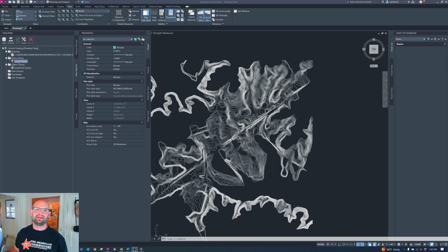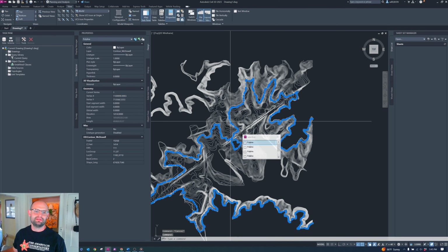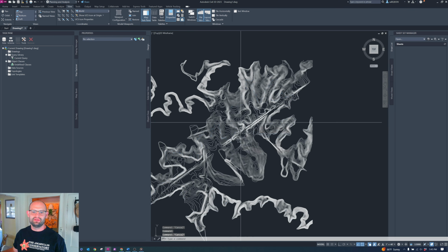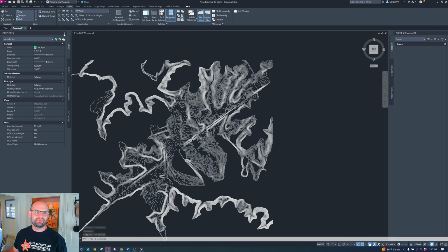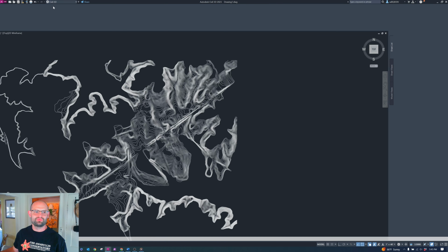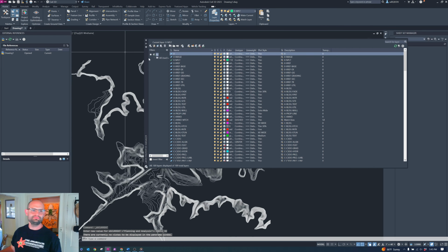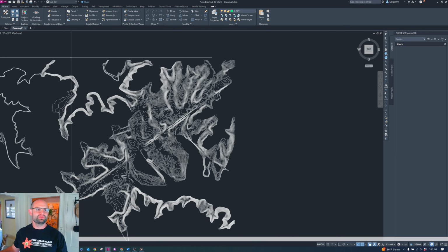Now that we have these lines live in here, I want to go ahead and detach that drawing so nothing funny happens when we start to create a surface. So right click over here, detach. They're here and will be unbothered by anything we try to do. Don't need the task pane anymore, and I prefer to work in Civil3D when possible. So I'm going to swap back to Civil3D. My favorite space has disappeared, but let's bring it back, and we'll do so with the button this time.